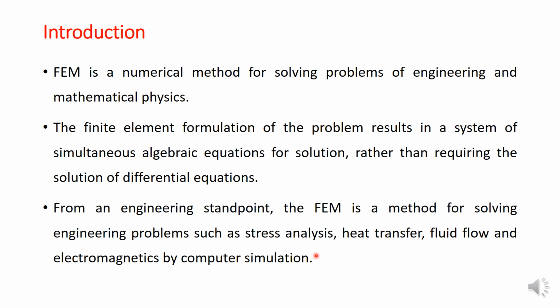These basic steps are common whether it is a problem related to stress analysis or heat transfer. The only thing that differs in all these areas is the governing equations. In the case of stress analysis, we use Hooke's law and the strain-displacement relations. But when it comes to heat transfer, we use a different set of equations, and so on. So basically, the steps are the same, but the equations used are different.